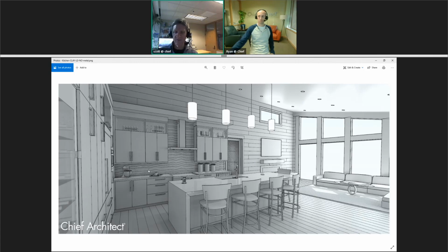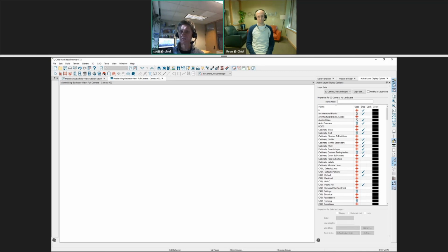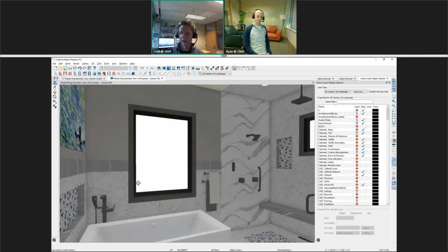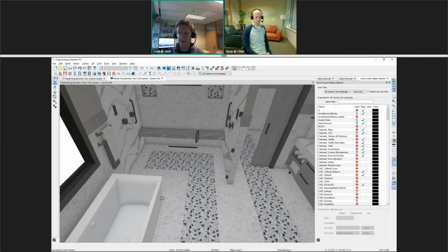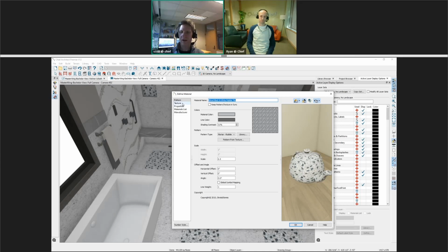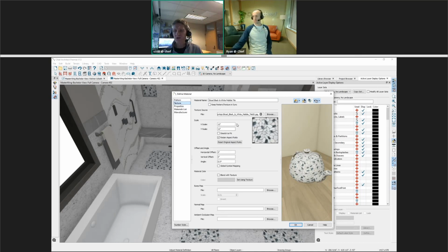Yeah, so Sean, thanks for your question. Sounds like maybe you have a couple questions here. Using the Adjust Material Definition tool, you should be able to click, and let's just maybe grab this tile down here on the floor. You can come in here and make adjustments on that material using both the pattern, which is in the vector view, and then on the properties panel or the texture panel, you can come in here and adjust the scale with it. If you need to take it beyond that, we do have a material player. The team will chat that out. That gives you more flexibility over what the materials are.